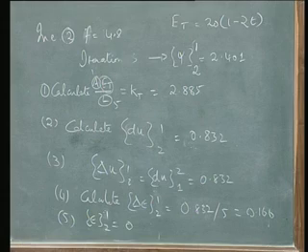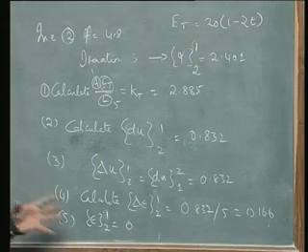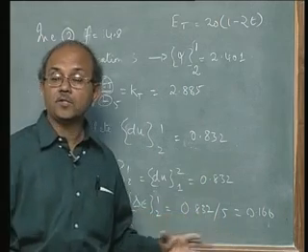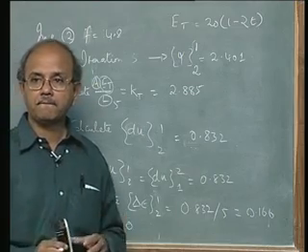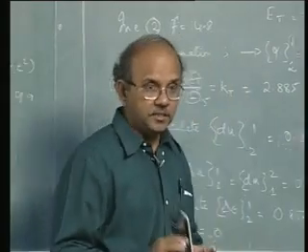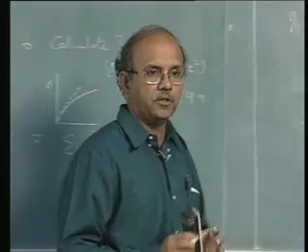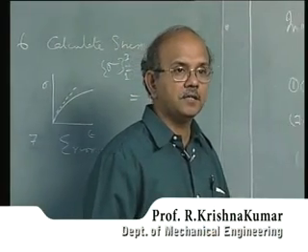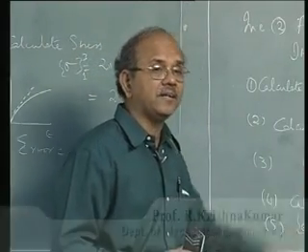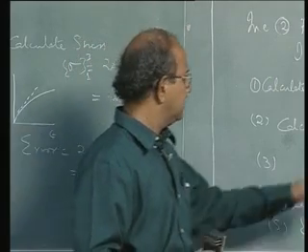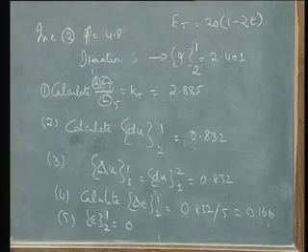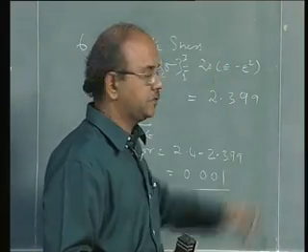No, this is not a finite deformation case, it's an infinitesimal deformation case because we are not considering the length change. We are considering only material nonlinearity, you are absolutely right, and we are not considering the geometric nonlinearity as it is called. Okay, so we are considering only the sigma is equal to 20 into epsilon minus epsilon squared case.